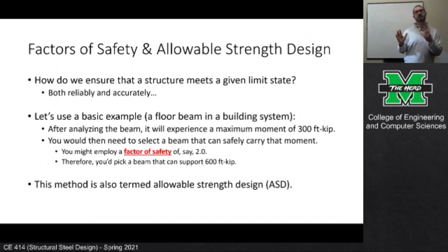And one of the ones that we experience as civil engineers is the land of geotech. In geotech, the uncertainty is so pervasive. You can do a boring here and then do a boring 20 foot away and get completely different soil profiles. There's so much scatter and so much variability that just saying, okay, we're just going to use a factor of safety of 3 and move on is fine and is still done to this day. But in structures land, we can get a bit more precise, okay?